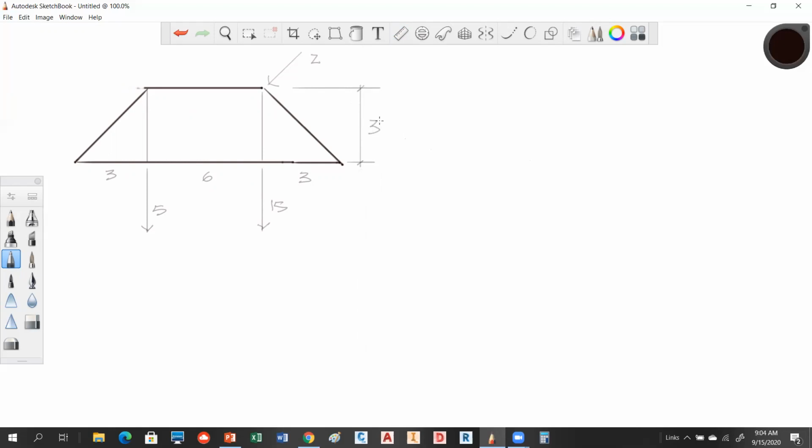All right, so there's my picture. Now I have a pin over here and a roller over here. The roller is such that this truss can freely move in the left and right direction. So we know that this roller is going to have to be reacting up or down. The pin also, it's a pin, so it's going to bring 2 reactions to the table for us.